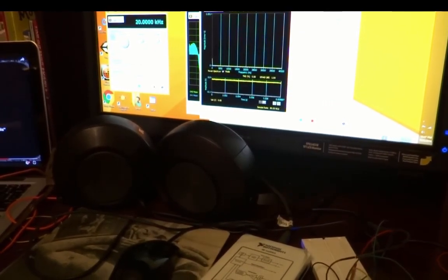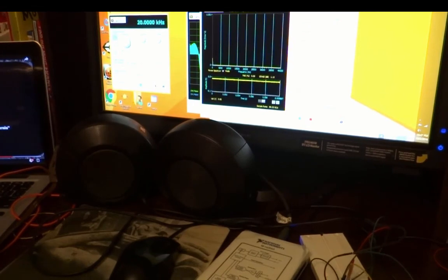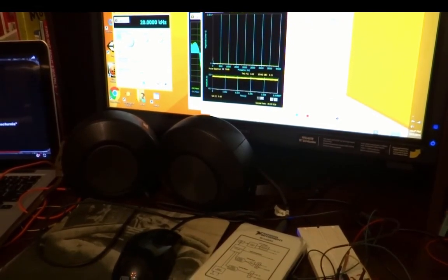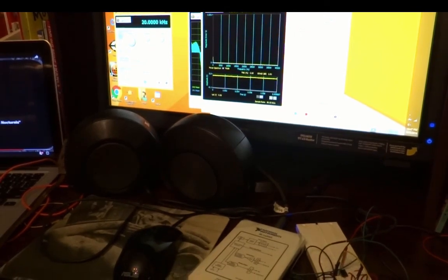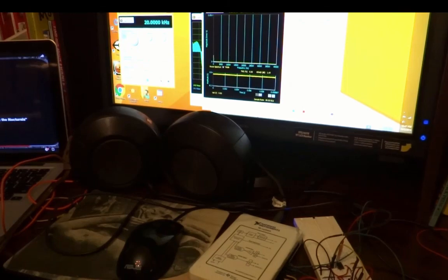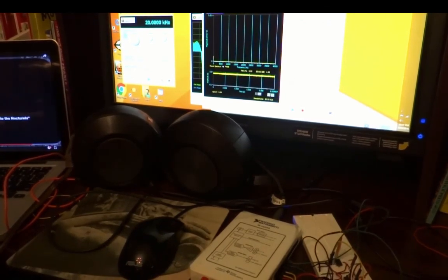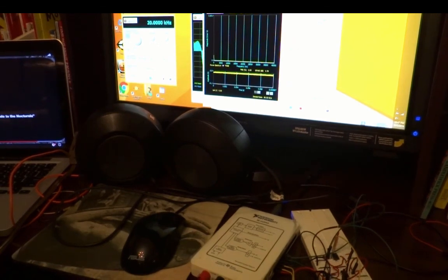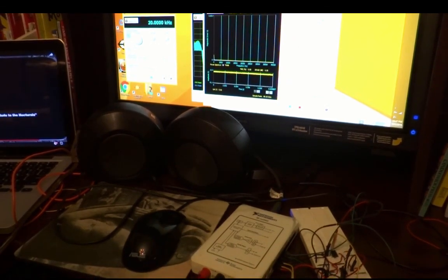There, what you do is of course, with all of this, you filter out frequencies that you don't need, and then you actually do a nonlinear operation. You take its absolute value, that's referred to as a rectification step, and then you filter that. So that might make another interesting lab that's a bit more difficult to mathematically analyze.